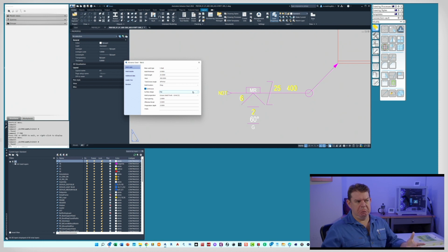For some reason it must be part of the coding that it just won't allow you to do it, and only site welds will show up in drawings that have been created by cameras for erection type drawings. So we haven't found a workaround for that as yet.